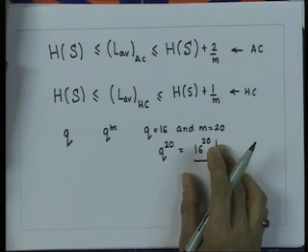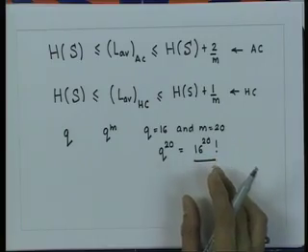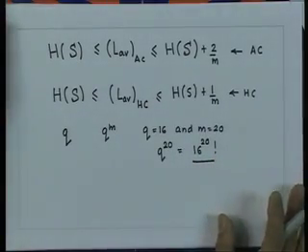Instead, we simply obtain the code word for the tag corresponding to a given sequence. Therefore, it is entirely feasible to code sequences of length 20 or much more using the arithmetic coding procedure. So, in practice we can make m large for the arithmetic coder, but we cannot do the same for the Huffman coder. This means that for most sources we can get the average length of the code closer to the entropy using arithmetic coding than by using Huffman coding.